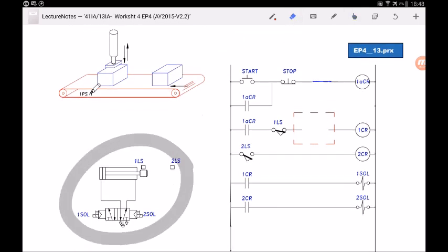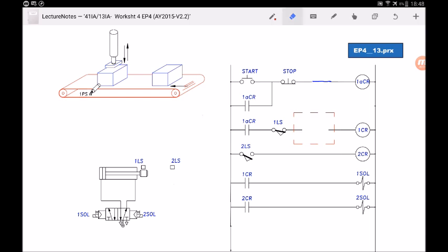So this is the pneumatic drive circuit, whereby you can analyze that the air supply of the directional control valve and the tubing is being wired to the rod side of the cylinder. So you can see that this check box actually belongs to second solenoid because it's closest to it. So when it is at this check box, the cylinder will retract because the air is going in from the rod side. So I will first label.